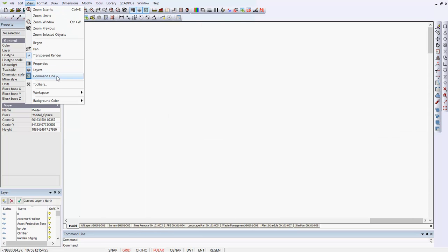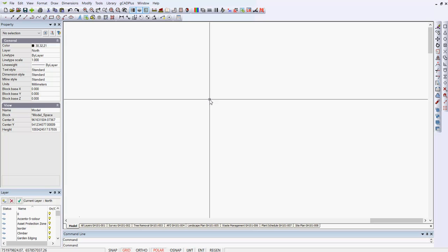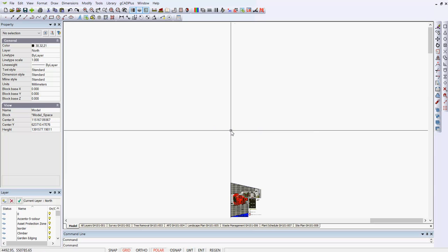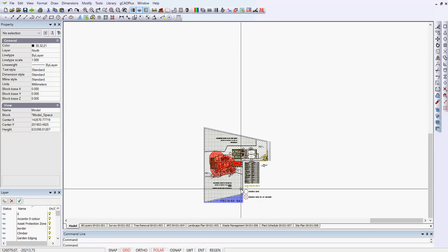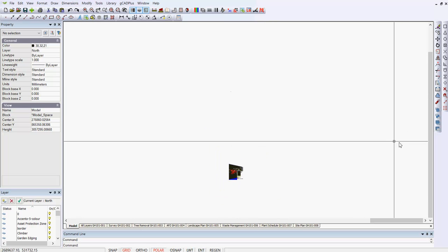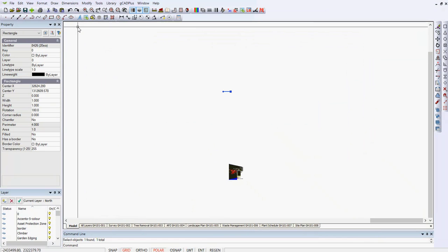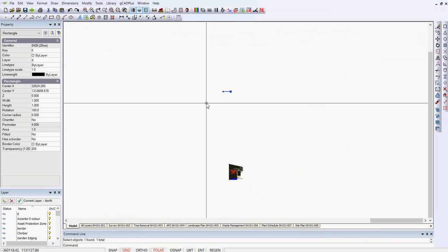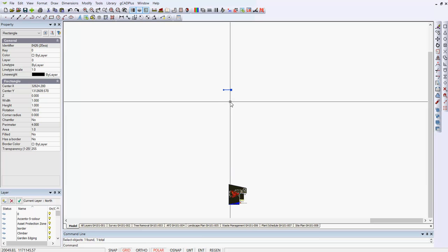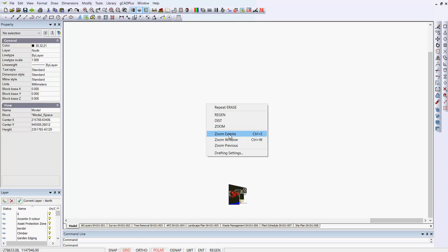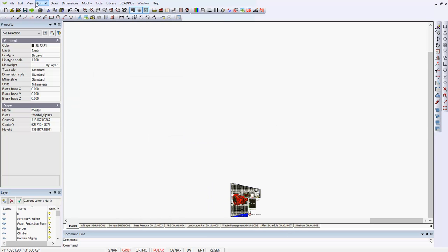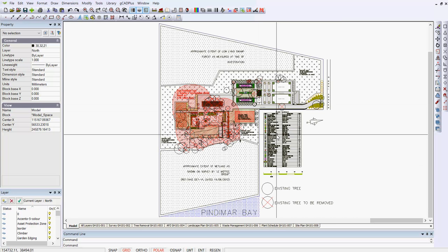If we go View and Regen, the whole drawing database, and then Zoom Extents, this time we do see the drawing, the design, but there must be something else up into this zone through here, and there is a rectangle that's way off beam, so we'll be brave and erase it. Now we'll Zoom Extents, probably need another View and Regen, Zoom Extents again. Finally, the drawing is starting to behave itself.